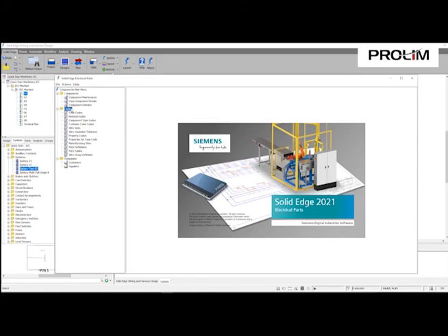One really key component of this software is that it doesn't allow you to have multiple parts with the same part name. That goes for the parts environment, the symbols environment, and even the design of the schematics and the wire harnesses. The system will not allow you to have two parts or two elements with the same name. If you're familiar with the other demonstrations that I've done, you're quickly advised that this part is red, it already exists somewhere else in the system. So, pretty key component there.